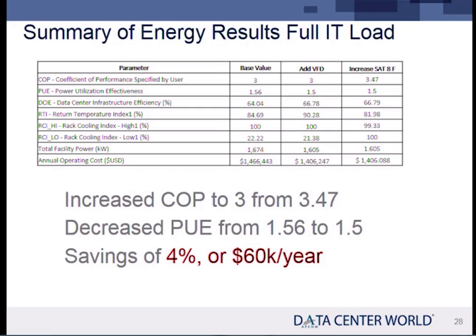So, in addition to that, I prefer hot aisle containment, because if you do cold aisle containment and your cooling quits, you're done. You're cooked, literally. But if you have hot aisle containment, then all your common area becomes kind of a storage location for cold air. He's absolutely right. Gives you a little bit more runtime. He's got more volume. What he's talking about is volume, the ability to share somebody else's air.